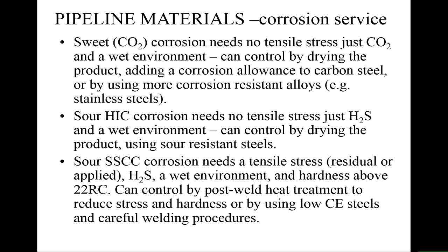Sour corrosion, particularly hydrogen-induced cracking, needs no tensile stress, just, again, hydrogen sulfide in a wet environment. Again, we dry the product, and there are steels which have been developed which are specifically resistant to sour corrosion.